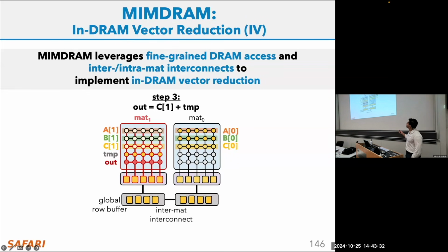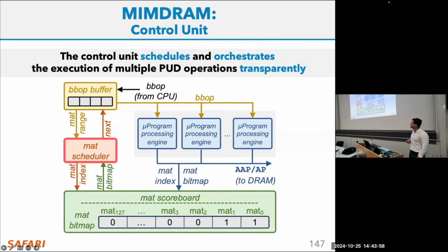I didn't draw the adder tree here, but hopefully when I say adder tree, you understand more or less that you spread the data and then you add one element with another element here in one level, and then another node here connects the outputs of the two previous ones, and you keep repeating that in that tree structure. I should have drawn this, I just realized that now. But anyway, hopefully it's more or less clear.